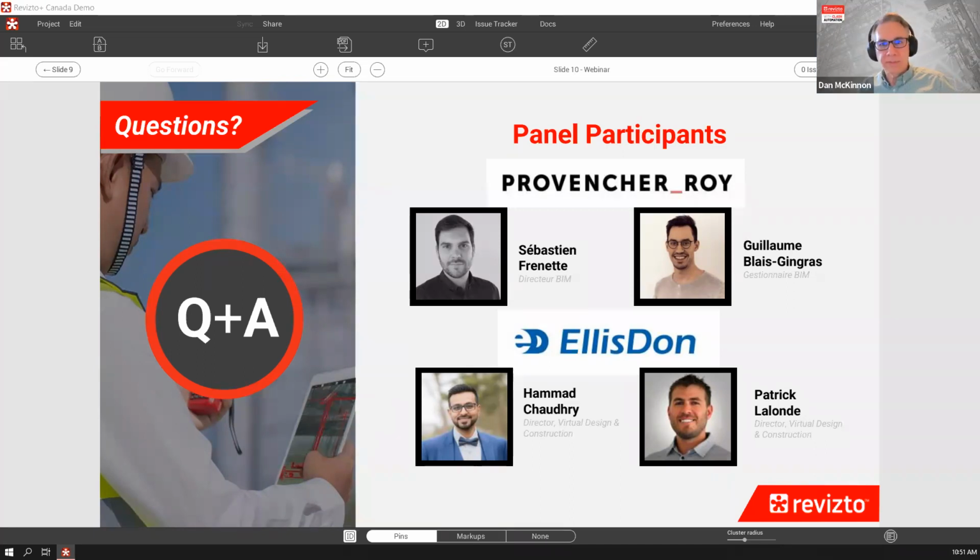Oh, go ahead. If I can add something, I feel like when we do clash detection, if we take the whole model against another whole model, then we hardly get anything useful out of it because it generates so many clashes. If we want to be able to leverage this, we need to split things up into smaller bits and pieces.